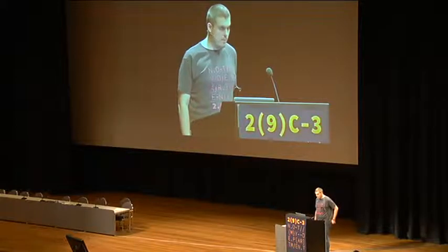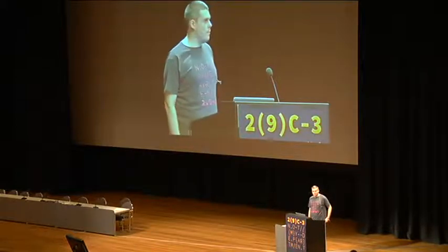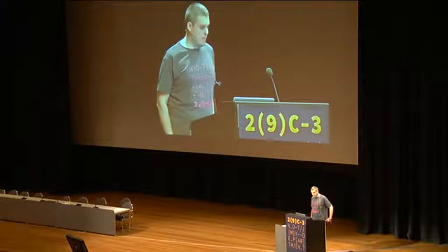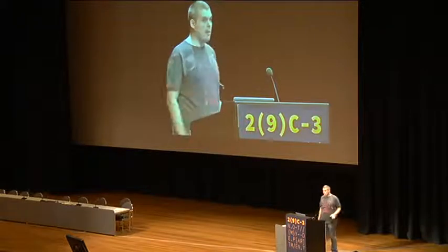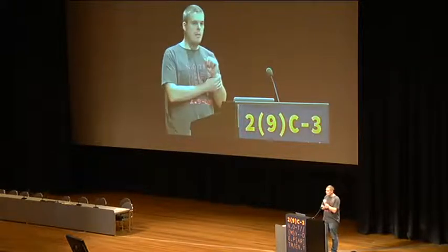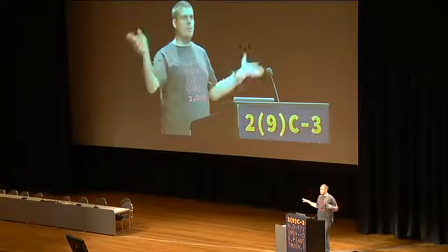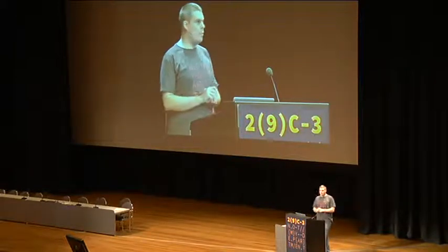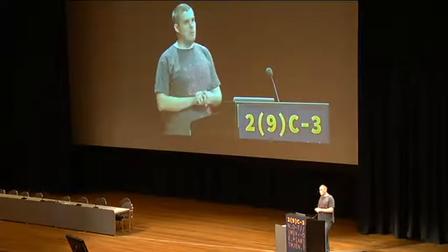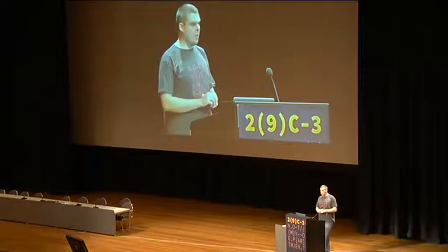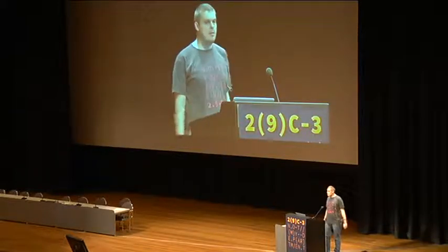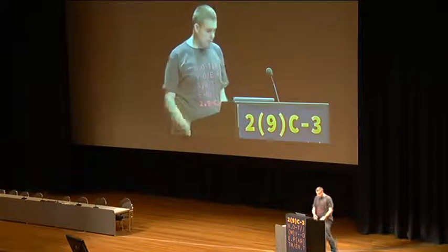Thanks. Do we have any questions from IRC? Hello, Internet. Okay. Yes? Do you need to rework the uplink filters on the Motorola phones to get this to work? Okay. On this phone, they are not. It depends on your application. If you're doing desktop testing or room testing, it's actually better to leave them on, because they help prevent the input front end from saturating. If you were trying to shoot for maximum distance, then you would remove them. But this phone doesn't have the filter removed, and it worked fine. So, yeah.